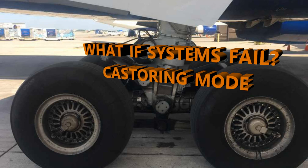Okay, all right, so let's go back to our lesson. Since I mentioned castering mode, it is just that. If you have a failure of hydraulics or just the system itself, then you're going to have this castering. It just means that the nose wheel can move freely in the direction of the aircraft moving.